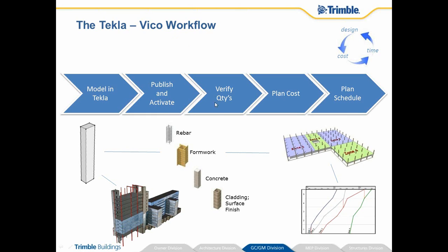And we'll verify the quantities using the takeoff manager, so making sure that all of the groups are as expected and highlighting as we expect them to use in the cost plan. And we'll actually build a cost plan, and we'll create some versions, and at the end we'll put everything together in the new task manager with some improvements that speed up the work with the linkage, and then quickly create a flow line schedule that then results in the 4D simulation.